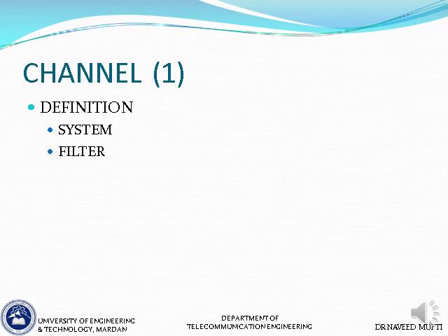You also have to appreciate that the channel more or less also behaves like a filter. Because it will not be able to pass all the frequencies, every channel has a certain range of frequencies that it passes without much attenuation or distortion. Other frequencies are not easily passed, either they are attenuated or distorted. So channels always have a band limited response. So in that sense they also behave like filters. That's what you need to remember as well when you're talking about channels. So effectively they will be behaving like filters.